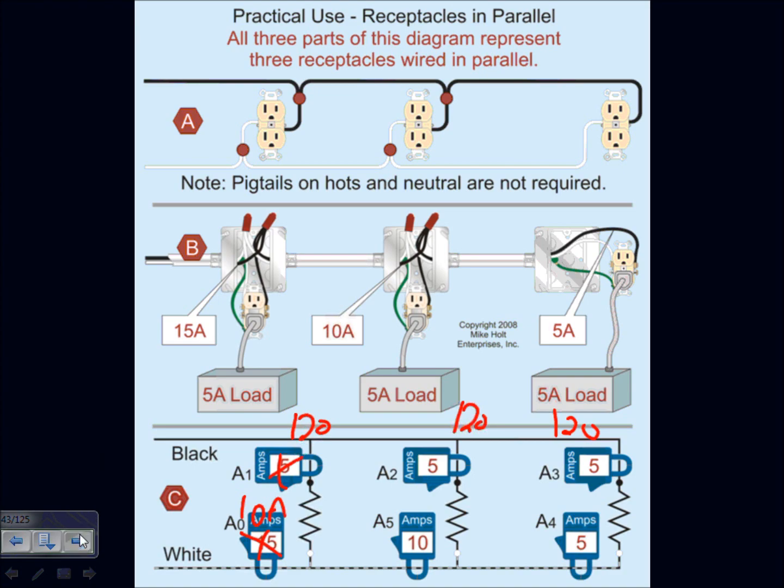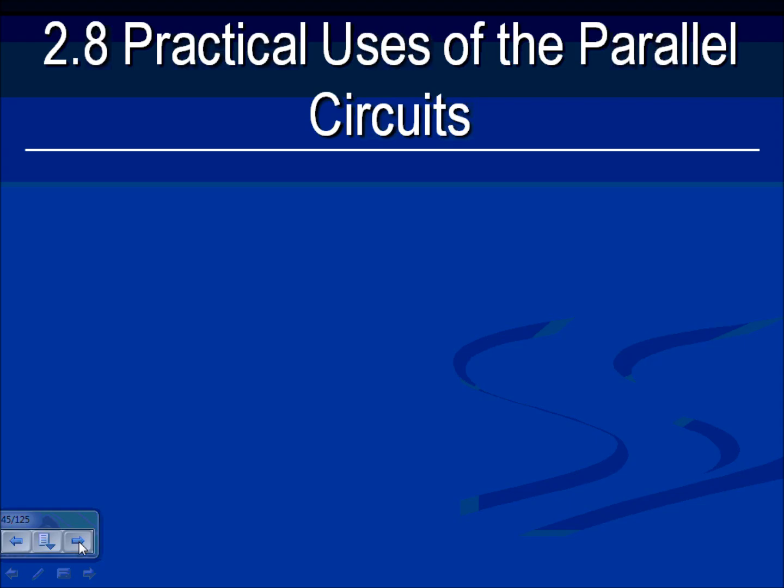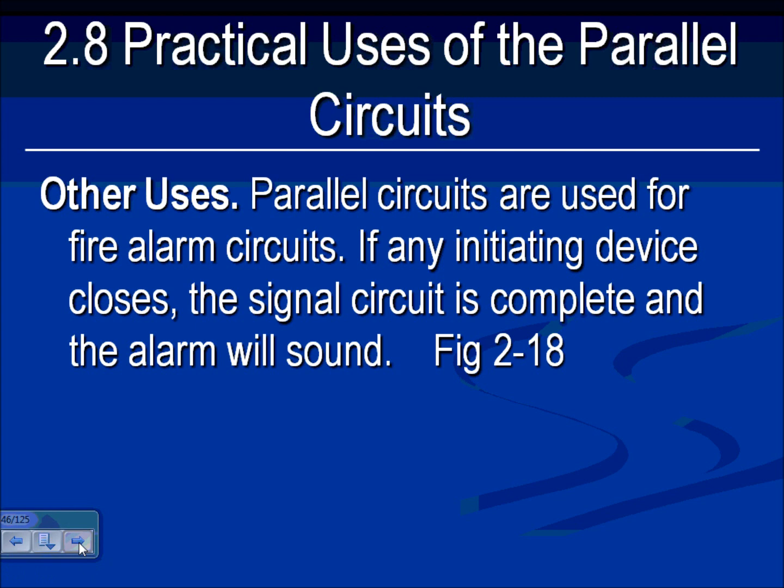on the system. It's not just fluctuate 5% and 10%. Lighting circuits. These are your lighting circuits that you design with Chad. The only thing that you can see that we put in series with the equipment. What is this? Control. Series becomes very big with control. The only thing that we did in series with the light here is what? Control. If you don't care about turning this light on and off, these switches, unscrew them, open the window, throw them out, and the circuit will continue to work fine. But you can't control it though. So these are for control. Practical use.